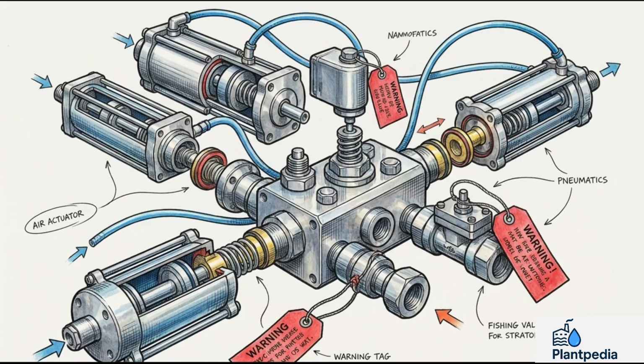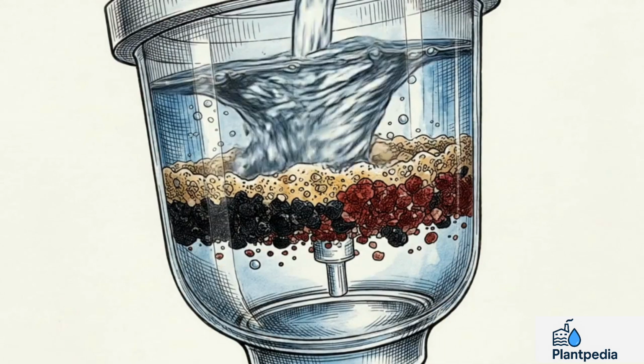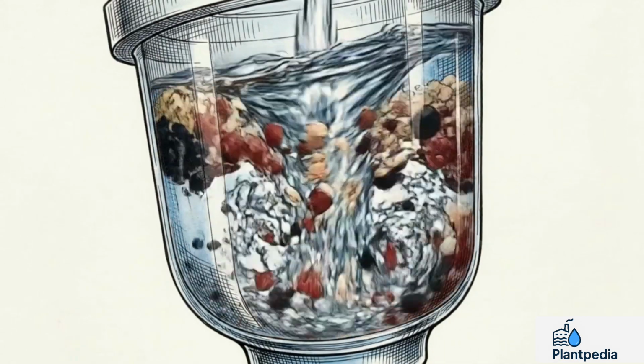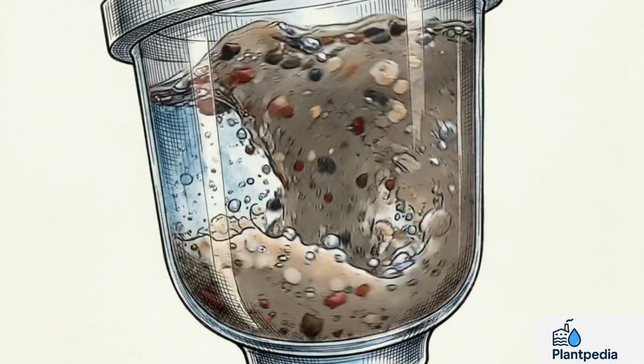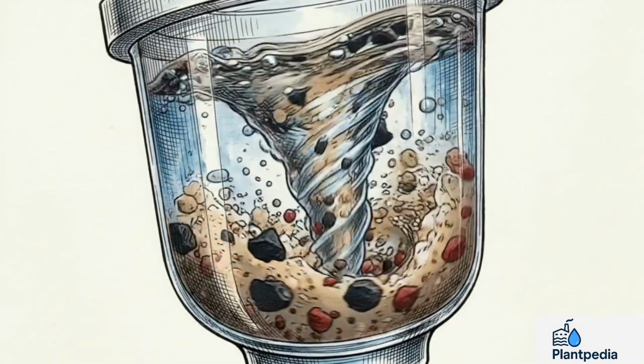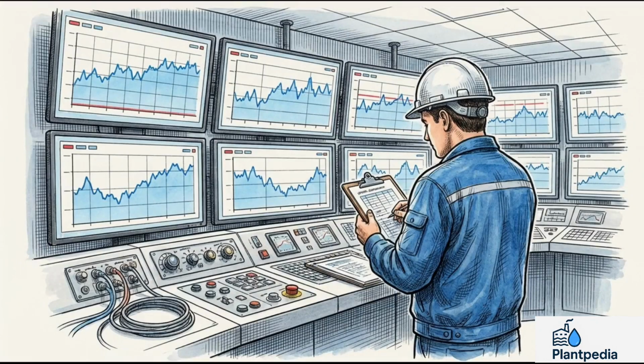An MMF requires the highest upfront capital cost and highly precise, complex backwash controls to manage three entirely different material densities without permanently mixing them. That operational complexity is justified only for facilities demanding maximum runtimes and ultra-low silt density index outputs to protect delicate